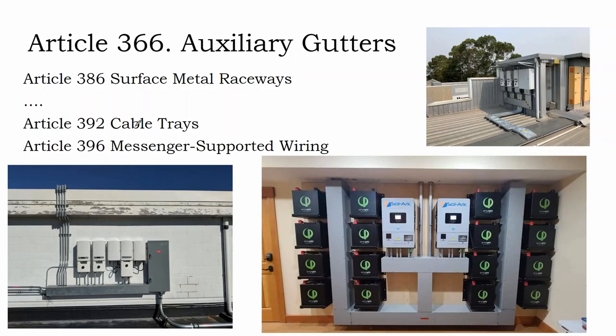Well, if you use gutters or cable trays, then you're just making this run relatively simple. There are parts in cable trays for flexibility, and then you can just kind of walk through and lay in and line the cable into it. So the actual cable run itself is substantially faster. Now, on top of that, getting all of this straight, making all the bends perfect, and all the kickoffs and setbacks is difficult.